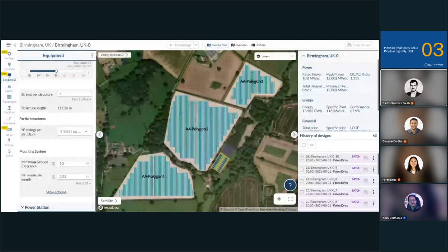Yes. So what we are trying is to combine PV with agrivoltaics, and by agrivoltaics I mean introducing animals in the solar farms as well. We are worried that the animals can chew the cables and jump onto the panels. So the idea is to raise this minimum ground clearance to 1.2 meters, which is already quite a lot.